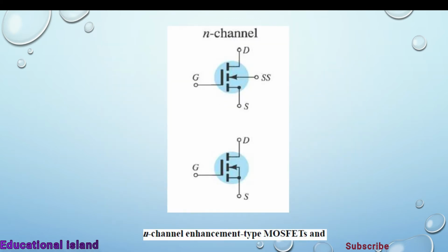And this is the symbol of E-MOSFET, the n-channel E-MOSFET. We can see that the dotted line shows that the channel material is absent. And if we short substrate and source, then we call it a three terminal device. Otherwise we normally say that it's a four terminal device, and the dotted line shows that the channel material is absent in E-MOSFET.